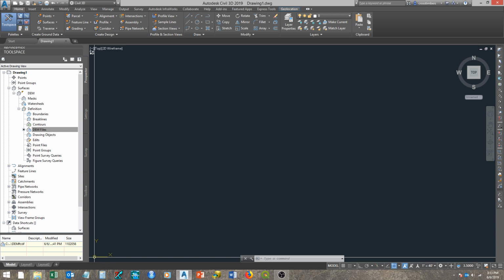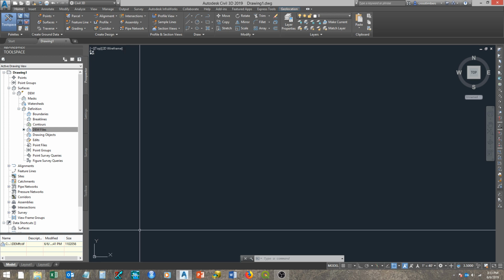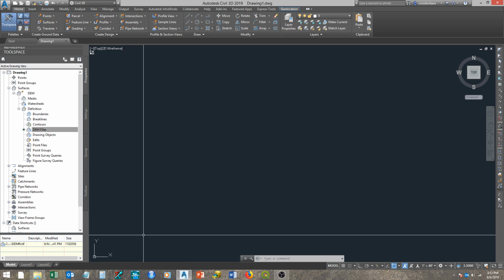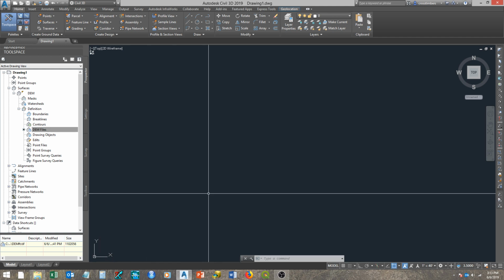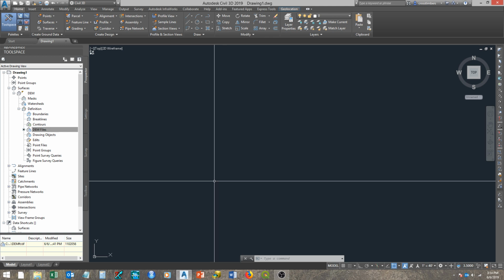This point right here is considered 0,0 in the XY direction. So even though you're on a set coordinate system, it still thinks your drawing is relative to 0,0. Most State Plane or NAD83 projections are very large; within a zone there are tens of thousands of feet, so we're way off the map as far as where it's zoomed into.